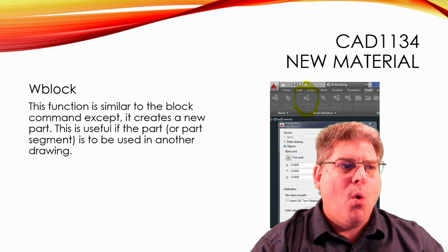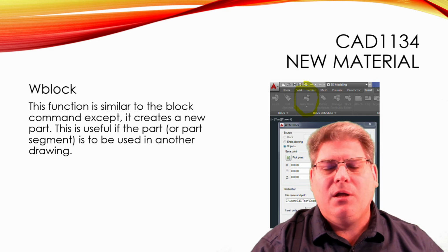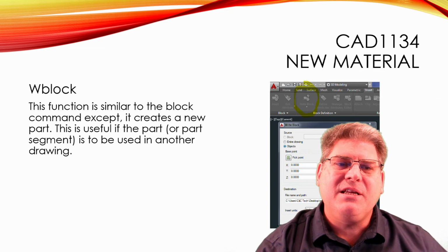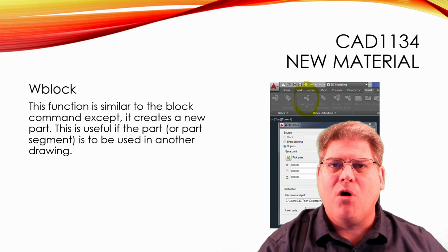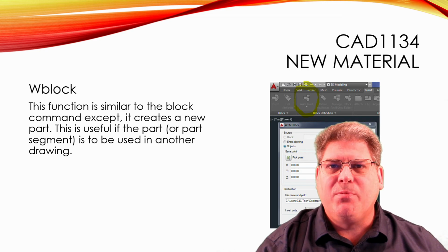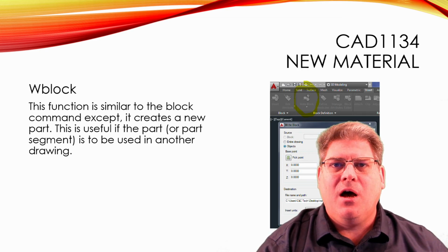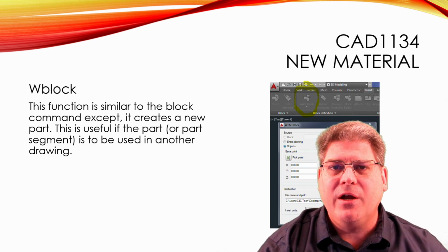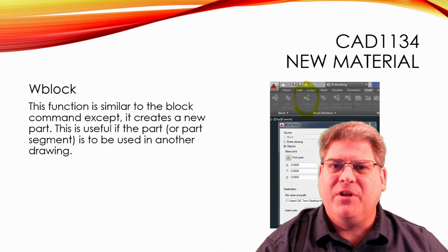Okay, so what is WBLOCK? WBLOCK is the same as the block command, but instead of it storing the drawing or the block inside your drawing, it will export it to its own little drawing. This is super useful when you have more complicated shapes than, say, a simple drawing of a diode, but it's something that you're going to want to use over and over again.